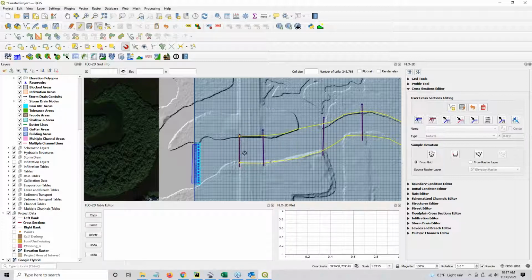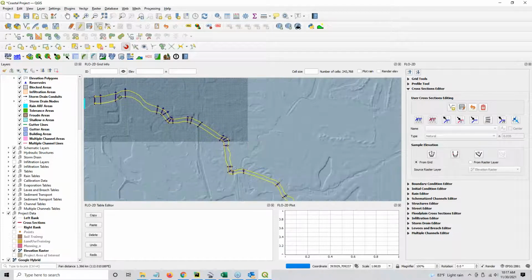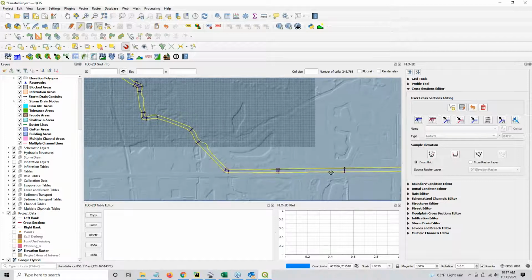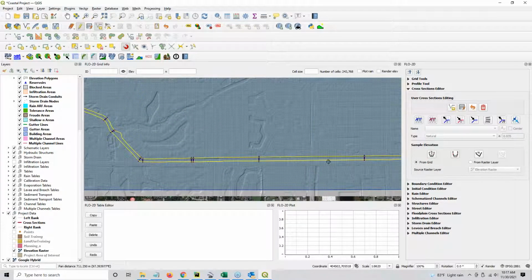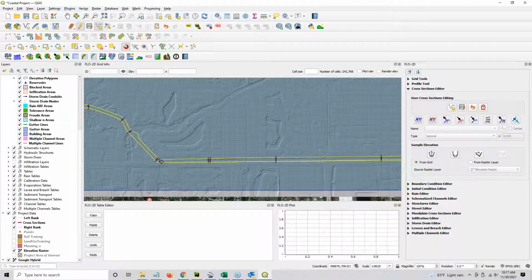I made my last channel just downstream of the bridge. Notice I just went ahead and built my channel through all the bridges, because this channel is pretty uniform and flat, so I don't bother with culverts and bridges that are wide open. I am going to put the weirs in, but I'm not going to bother with those big culverts and bridges that are wide open because it's such a flat channel.